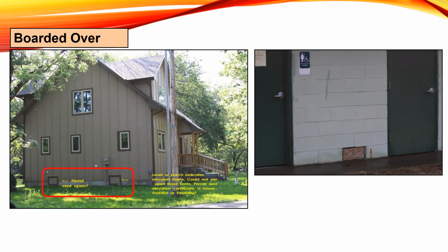A good option for someone like this that doesn't want the flood openings could be to have engineered openings. Those automatically open and close with the rising of floodwater. They don't require any human intervention for them to work. They're a little bit more expensive, but you wouldn't have to worry about any of the other issues with having the open hole into the enclosure.